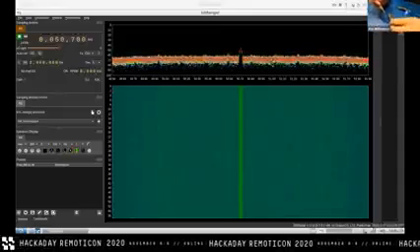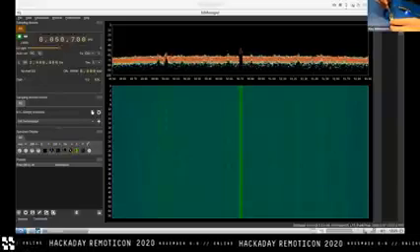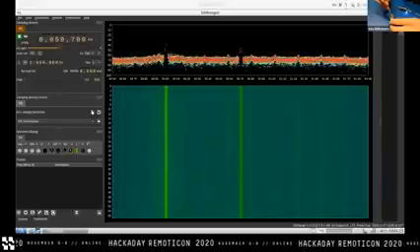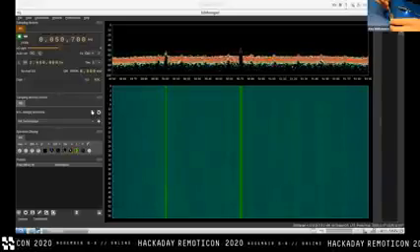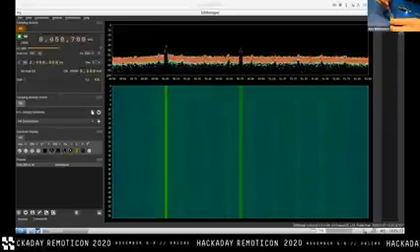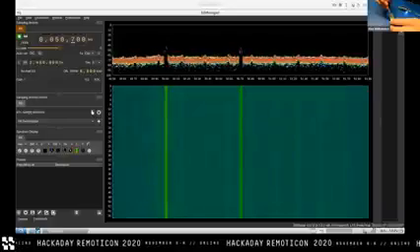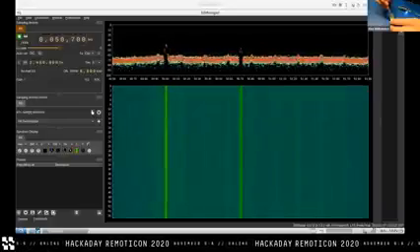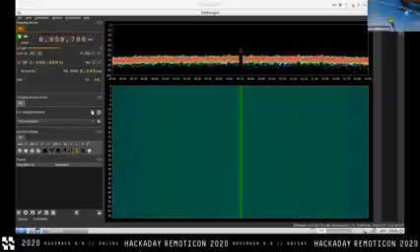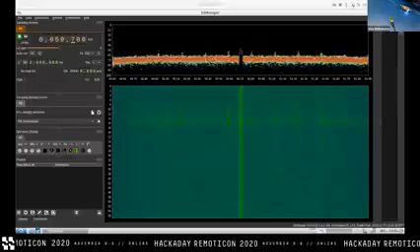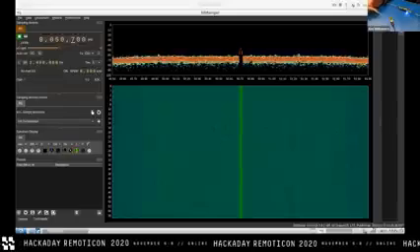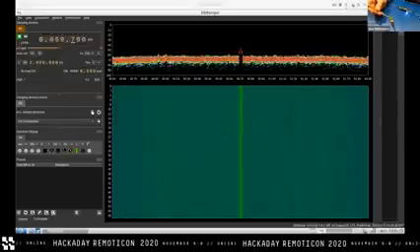Okay, cool. So we know that the pin is up here somewhere. If I stuff my probe, oh, look at that. Somewhere right up along that edge, there's a nice bright 50 megahertz signal. How about that? Cool. So we've isolated exactly where that 50 megahertz signal is coming from. I don't want to spoil the fun, but you can start this now. The sort of Easter egg hunt is this signal is actually being piped out to a different place as well.